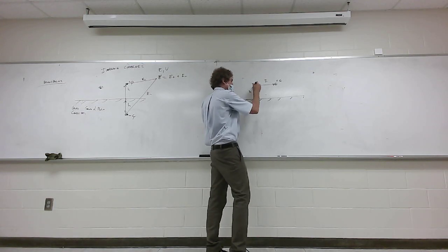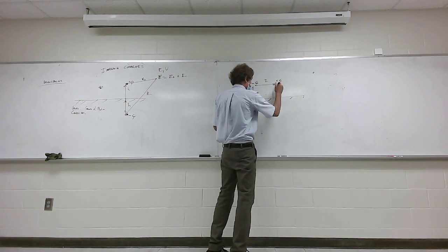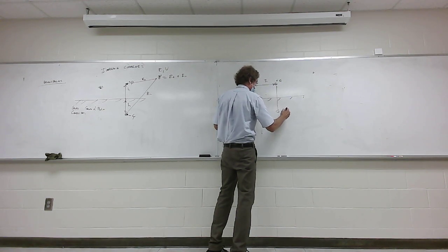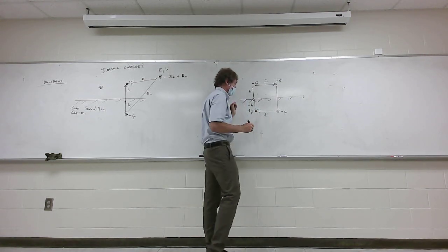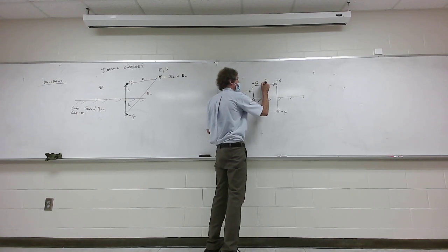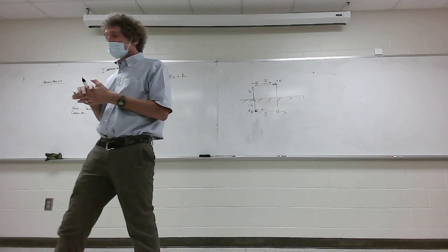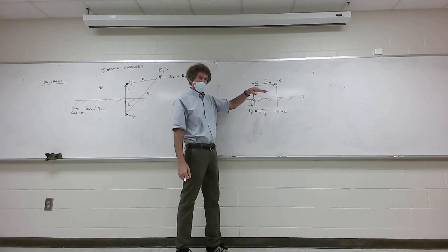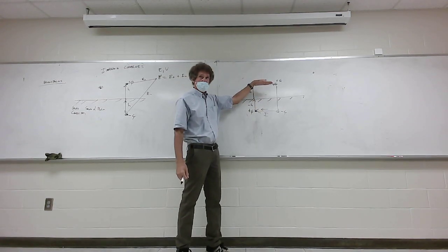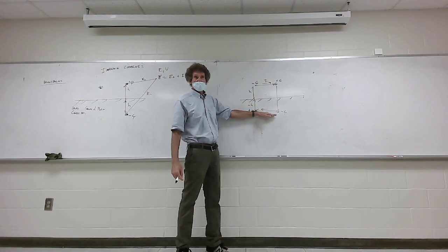Now, if you have negative charge here, if you go a distance minus h here, that would image as positive charge here. Positive charge here, it would image as negative charge. And you can see that the image of current that would be developed, here current's flowing this way, this current would be flowing this way. Y'all see that? The point I'm making is that if you have current above a ground plane parallel to it, it images in the opposite direction below the ground plane.